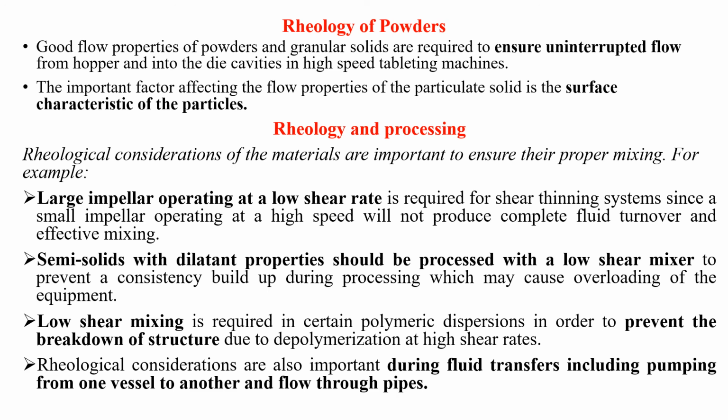When these impellers are run at very high shear rate, it actually changes the viscous nature of the material. It could either increase or decrease the viscosity based upon the nature of the material. So it is always better to run the impeller at very low shear rate. Always make sure the mixing is done at low shear rate.